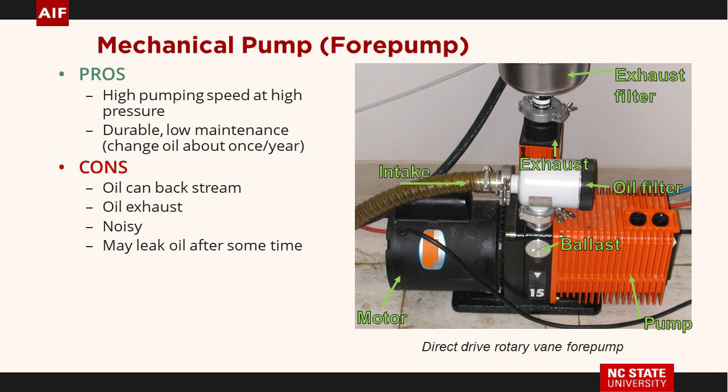And I've gone to people who said, my pump's not working right, my pump's not working right. They're pumping just air and they've got the ballast open. So they're making the pump work double time. So look and see if your pump has a ballast on it and what the setting is and mess with it so you understand what it does. But that's how you help take care of nasty gases.